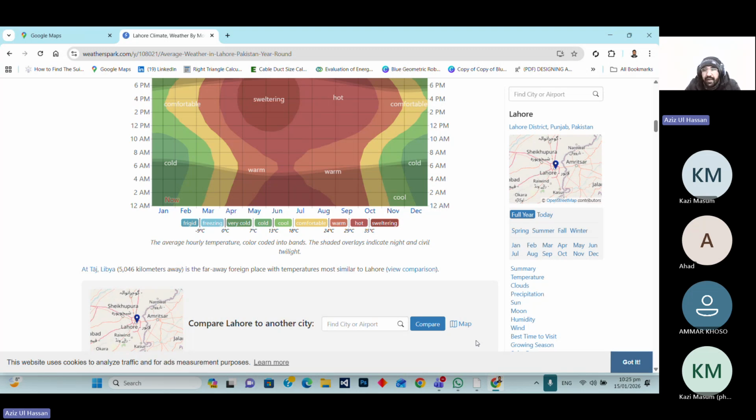In the night time, the temperature may go to 0 or 2 degrees centigrade, but at that time the irradiance should be zero, so the inverter is not getting power from the solar side. But in daytime they get the light and convert it into DC and AC power, so at that time temperature is the effective one.